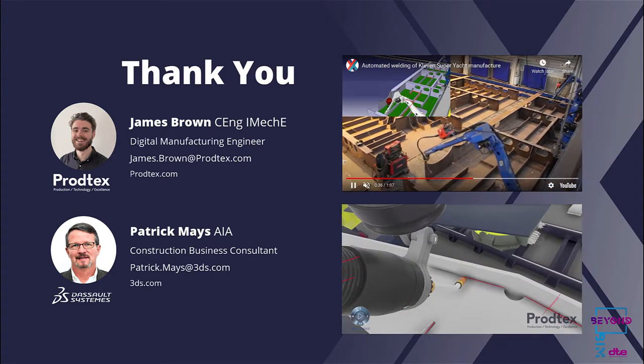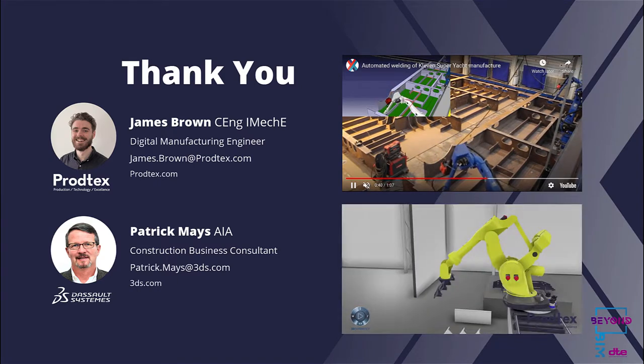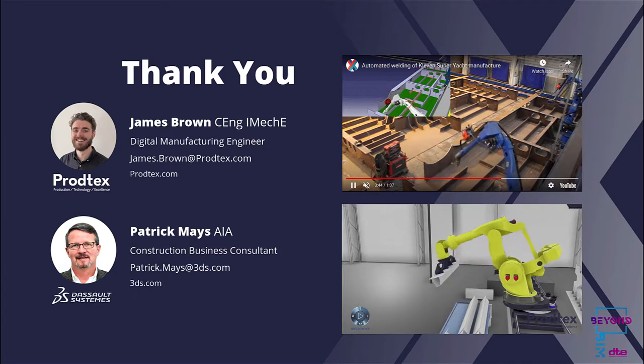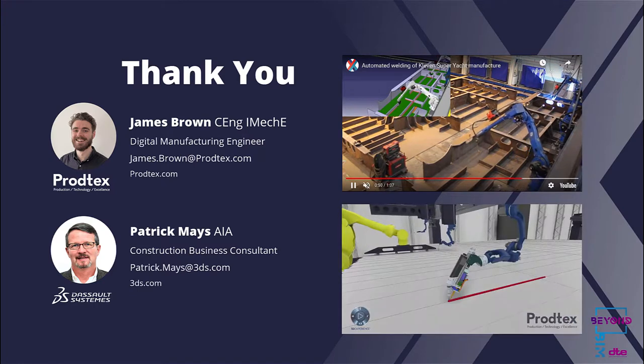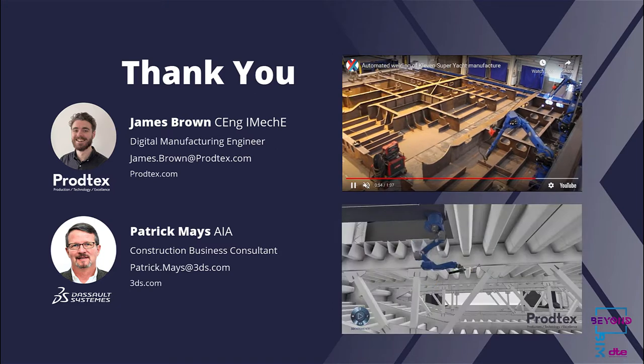In addition to stairs, today we talked about different types of slabs, finished slabs that you can walk on immediately, or slabs with exposed rebar that are a lighter weight product. We talked about twin walls, walls that are fire separating key areas of the building, partially made in the factory, partially poured in the field.